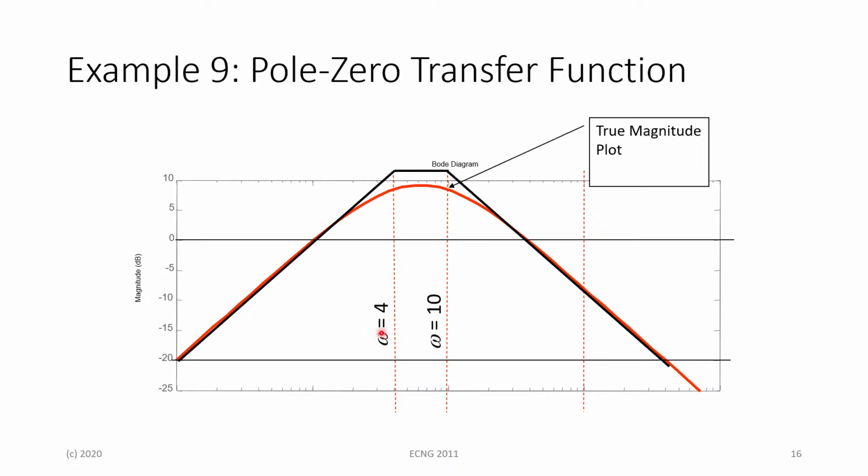So we have two corner frequencies here, being omega equal 4 and omega equal 10 for that magnitude graph. The only time when you'll have a single corner frequency is when the entire system equation is of order 1. But when you start increasing in orders, you will no longer have one corner frequency. You will have multiple corner frequencies in particular.